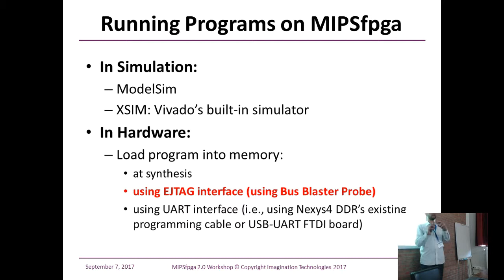We have a Verilog module that takes data from TX/RX and puts it in the scratch memory. So you don't need a bus blaster if you just want to load code. You can load through the UART, but you can't debug through it. It doesn't stop the code and doesn't use the JTAG interface. It basically is a back channel into the memory system itself.